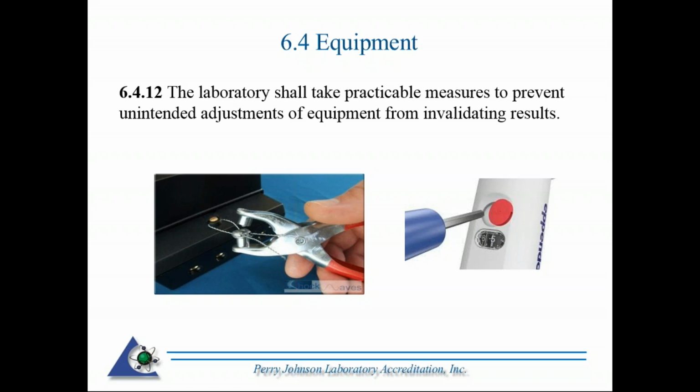To the right is a pipette calibration. There's often an adjustment that can be turned to increase or decrease the volume. Typically, that should be covered up with a seal. If that seal is broken, then the integrity of the traceable results may very well be in question. Oftentimes the calibration provider ought to seal these for you. So one thing you may want to make sure of, when the equipment is brought back, if you know where those adjustment mechanisms are, is that they are sealed.